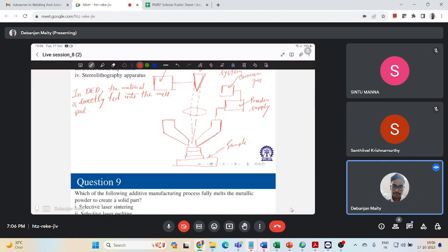So, can you tell me a little bit about the difference between laser melting and electron beam melting? If you see the selective laser melting system, it uses a motor-driven mirror system to deflect the focused laser beam at different points on the powder bed to develop the structure. Whereas an electron beam melting system generally requires a vacuum in the build chamber, since the mean free path of the electrons at sea level in atmospheric pressure is only a few microns, right? So you have to have a vacuum chamber.